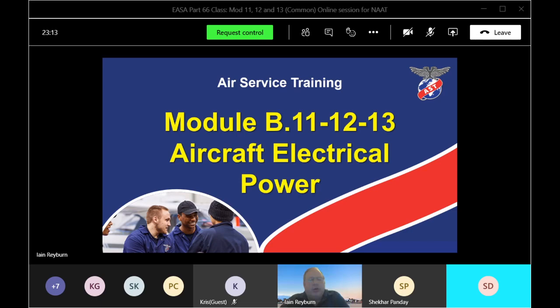Now, what else could have caused these contacts to open? One of the things is called G-forces. Okay, you hit a pocket of air, you get the G-force. There might be enough G-force to actually cause the contacts to open, and you lose your power supply. Or in faster aircraft, you do turns, you might actually have enough G-force to open it. So a latch contactor, if you look at here, I've got a latch. So when I energize it, it comes down and physically locks. It's a mechanical latch. So the first thing is the latched power contactor is not affected by any G-forces. And the second thing is, to keep this type of contactor closed, I need a current to go through that coil all the time.